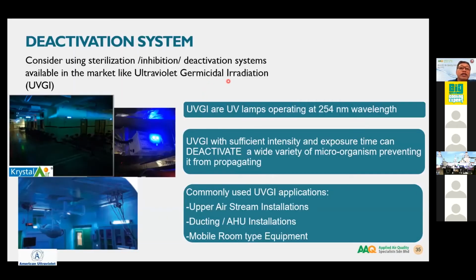So the activation methods that we have: this is an OT room, this is a duct decontamination for the supply air duct. Of course, certain buildings may not have an aircon system, or may not install only AAQ. Sometimes they add on fan coil units, FCU. For an FCU, there is no space to install on-coil decontamination equipment.